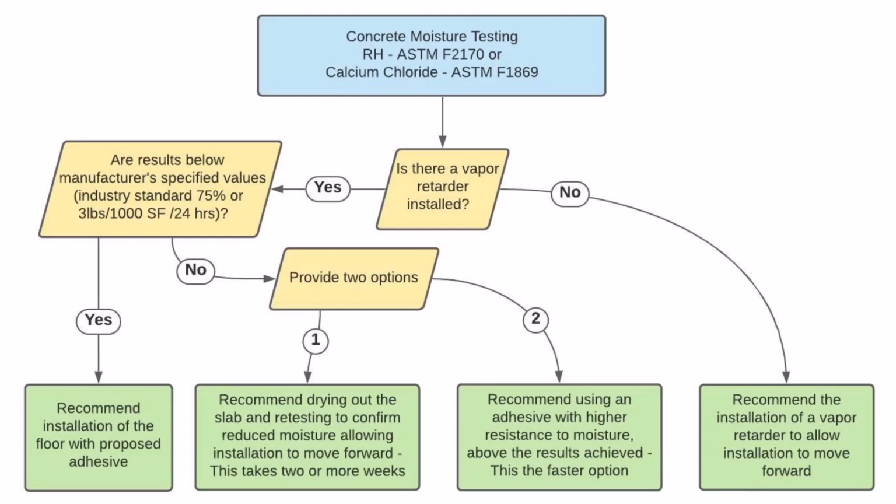What that's telling you is after installation of the flooring, the equilibrium of the concrete slab relative humidity will be whatever your tested value is. That's the research based on the depth of the slab. The research has indicated that at that specific depth, that is representative of what will be the equilibrium.